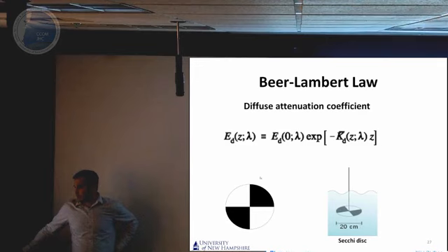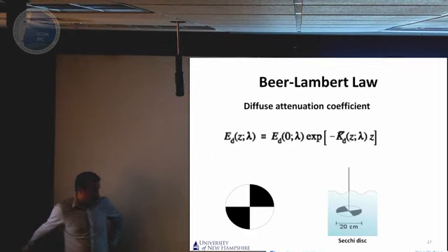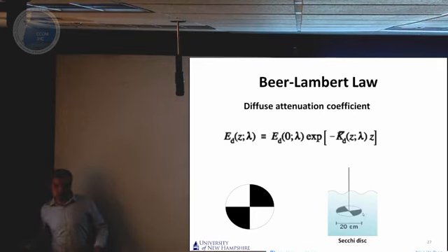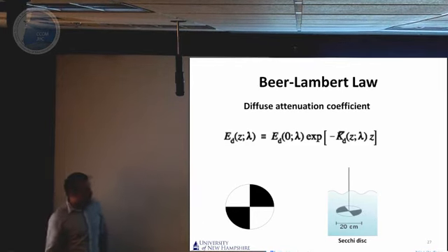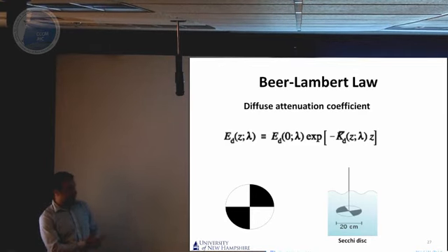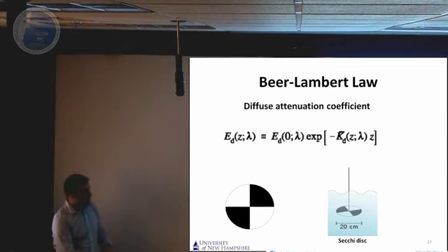In traditional methods, the diffuse attenuation coefficient was calculated using a Secchi disk. The Secchi disk was mounted on a pole and released into the water, and the distance where it could not be seen anymore is the depth of extinction. That's how they defined turbidity, but of course it's very subjective to whoever drops it into the water. So it's possible to get empirical measurements of the diffuse attenuation coefficient, which is especially critical in our research, because it lets us see what kind of environment is going to attenuate how much of the intensity.